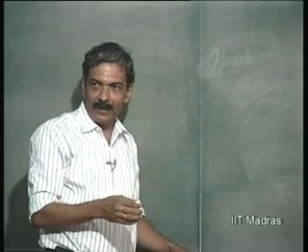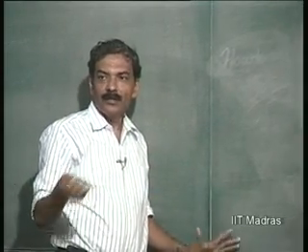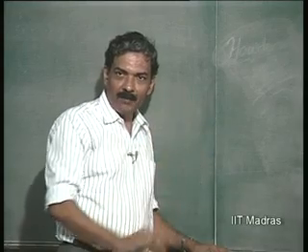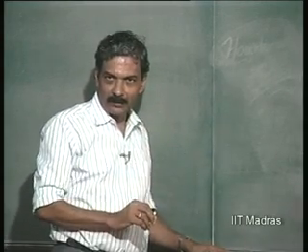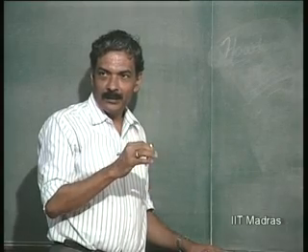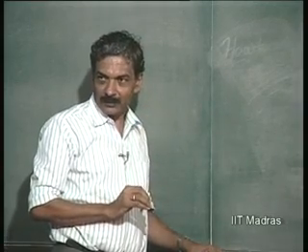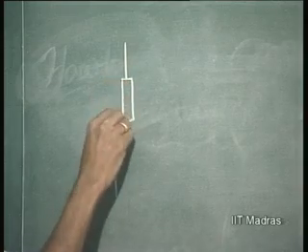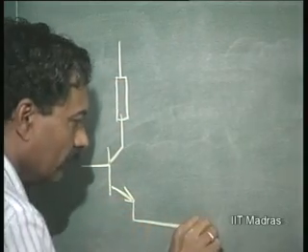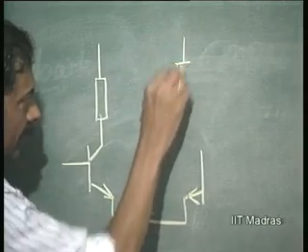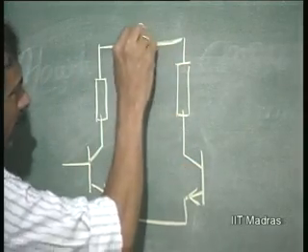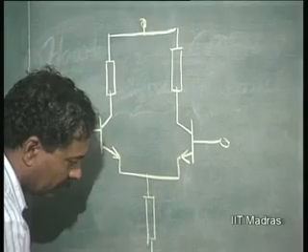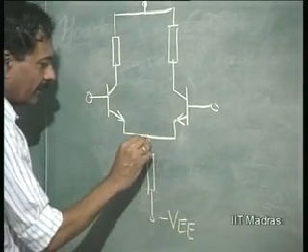Now, we are going to consider the differential amplifier in general for large signal. I am not going to assume any small signal model. We have assumed a model in the earlier situation that the common emitter amplifier can be replaced by its model, which is delta VBE into GM as a current source at the output. Now, we are not going to assume such models. Therefore, in general, for a differential amplifier, let us see how the output versus input characteristic, that is, the transfer characteristic, looks like. This we had seen for common emitter amplifier, etc.